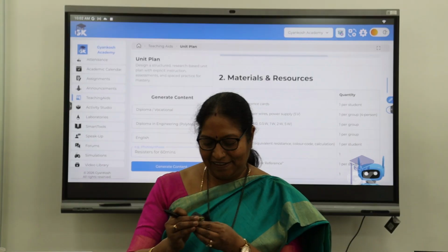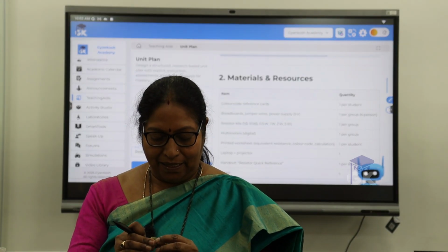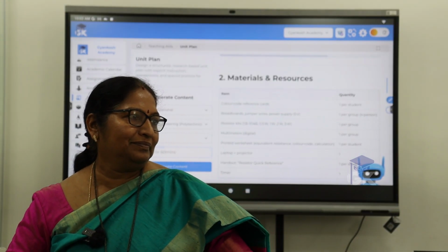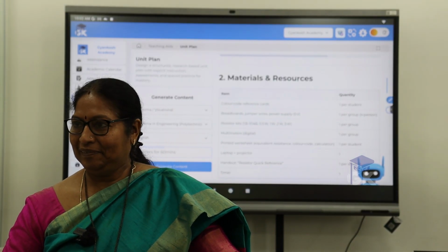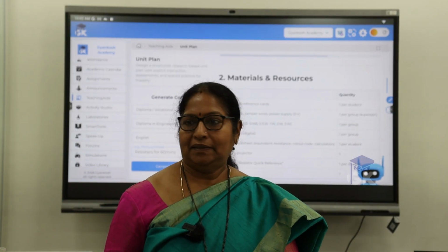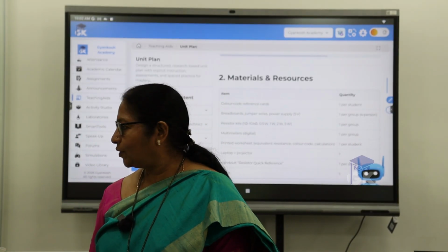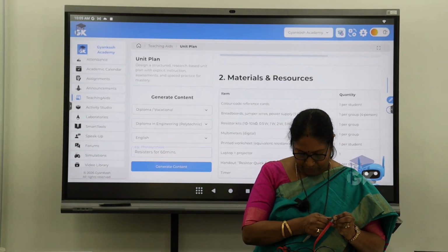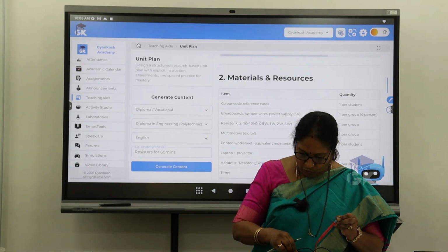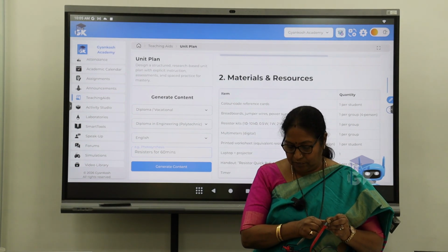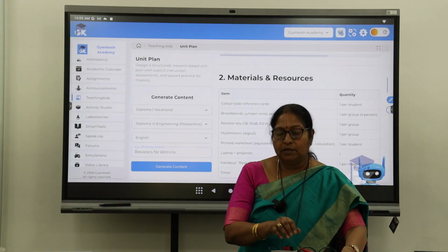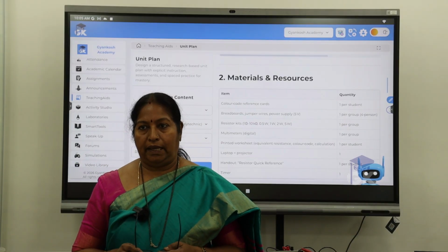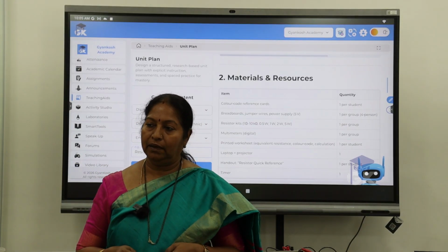Just see there. 5 watt. What is it that has been written? 0K5. Can you just see that? Did you take a multimeter? This is a 500 ohms resistor. So 0K5 is written there, which means 0.5 K, which is nothing but 500 ohms.